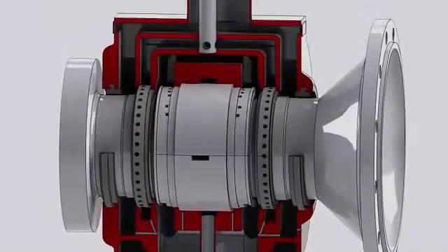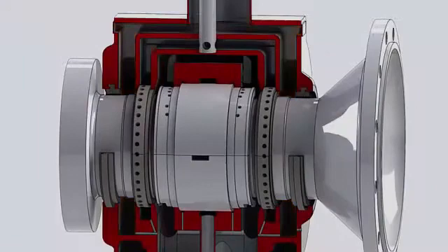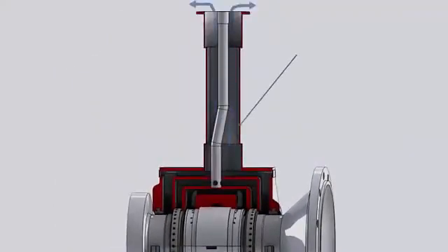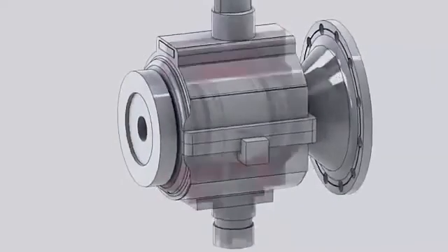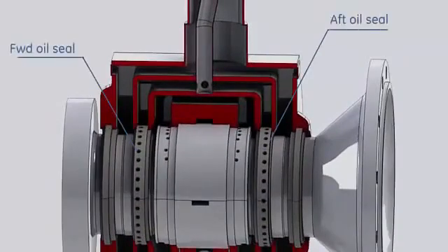Bearing 2 has a vented cavity. The compressed air leaking from the outer labyrinth seals is vented to the atmosphere through a vent pipe mounted on the top of the housing. Inboard of the outer air seals, two pressurized labyrinth seals are located for lubricant control.